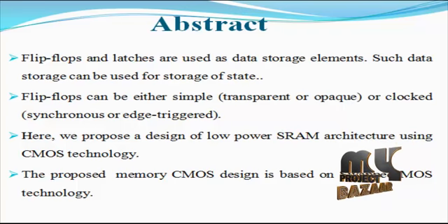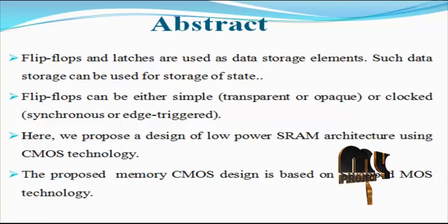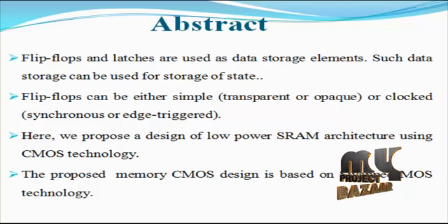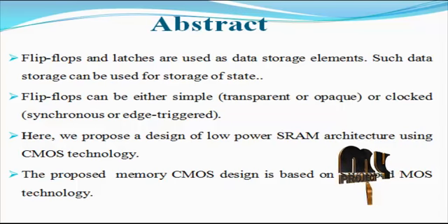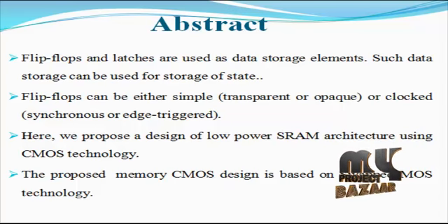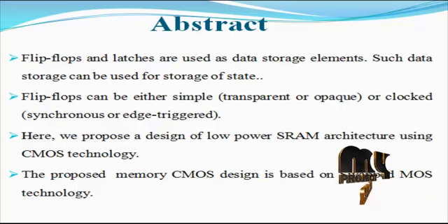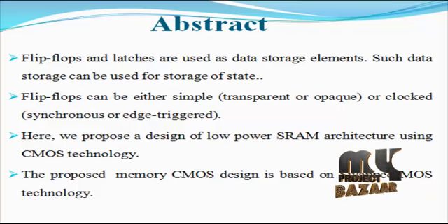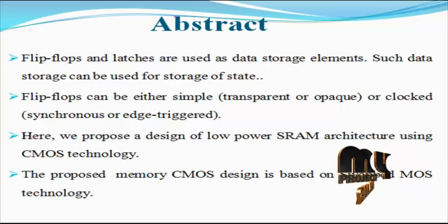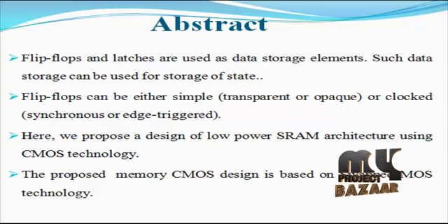The most commonly used SRAM type is the 6T SRAM, which offers better electronic performance in all aspects: speed, noise immunity and standby current. The smallest 6T SRAM cell fabricated till today has an area of 0.08 micrometer squared and was developed in 20 nanometer technology based on our proposed designs.